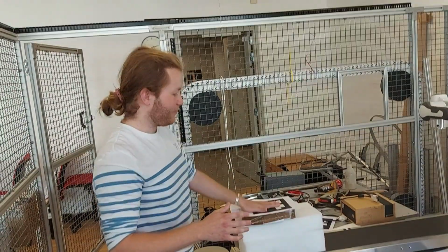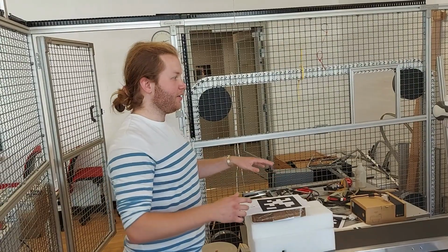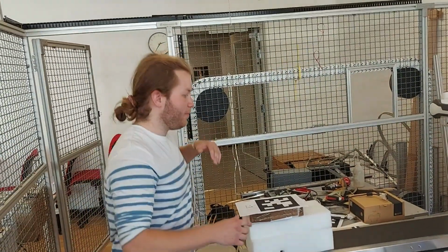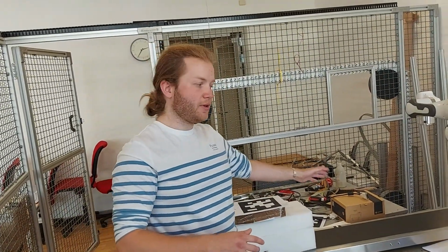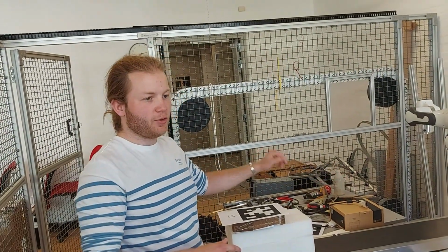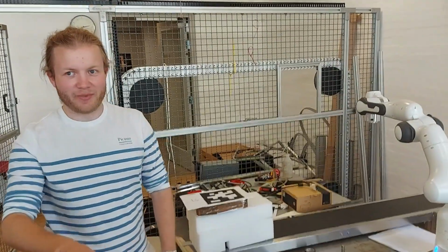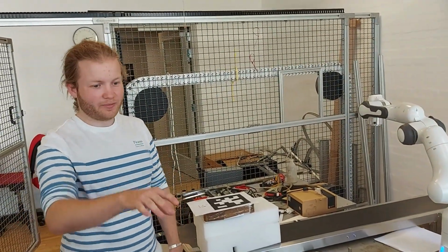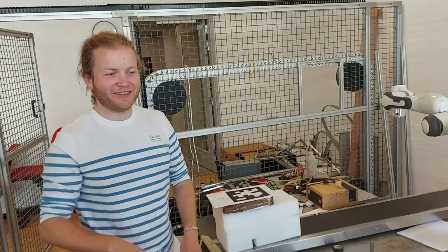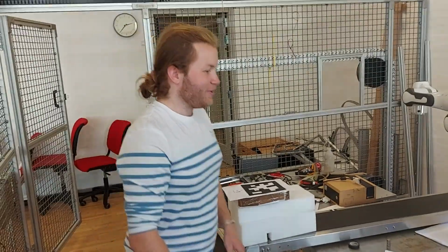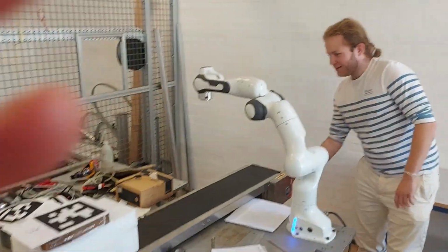So instead of using this block as the target itself, I disable the robot arm, pass the ArUco tag through to roughly where the robot arm would intercept it, and then I block the tag so that I ensure it's only the Kalman predictions that are being used without measurement updates. That's also how I made the measurements for the report. I've put the measurements into the report now, so you can see them. They're not finished, but the lines and stuff are there. It might overshoot and hit the block and stop, but we can try and see it in action now.